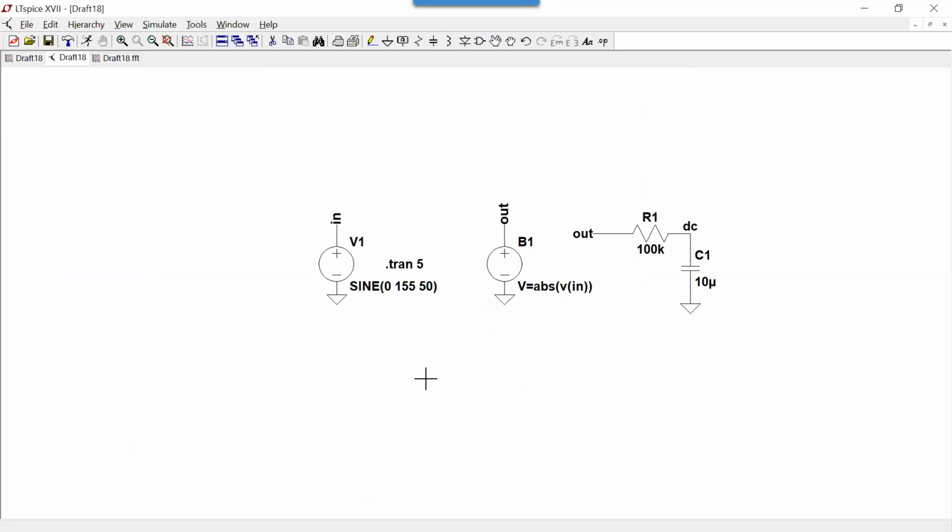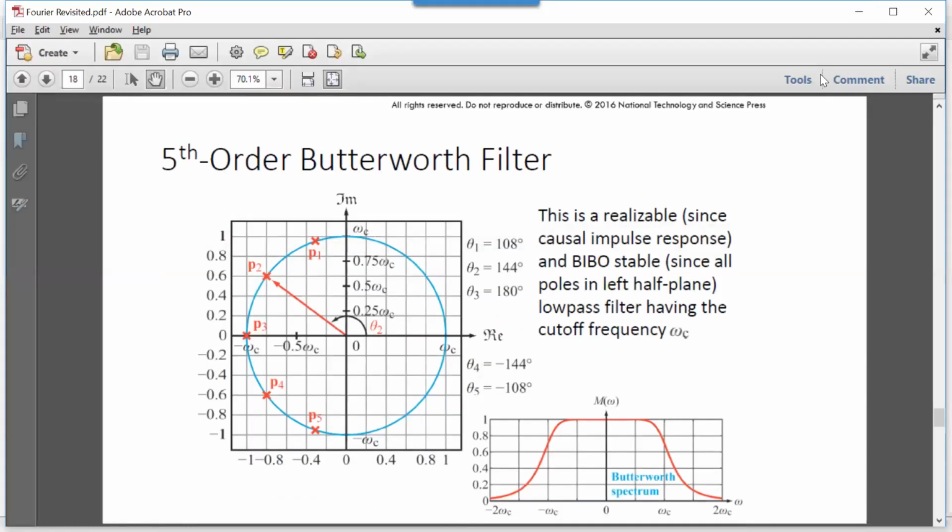And basically what you can do is have an op amp with a really large gain. So even if you're getting a small sine wave, that small peak will be amplified to the rail, and then you get basically a clock signal. Okay, so that's the first application. Any questions so far? Alrighty.